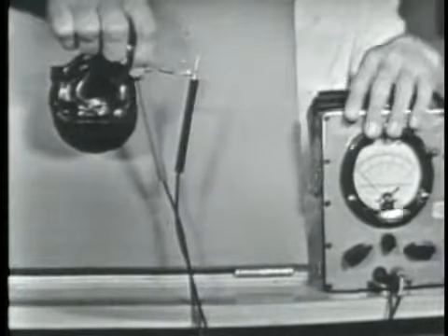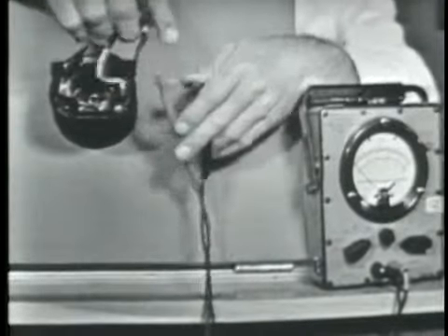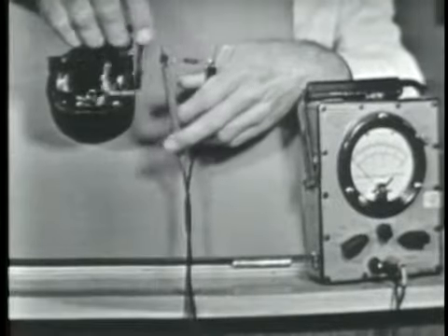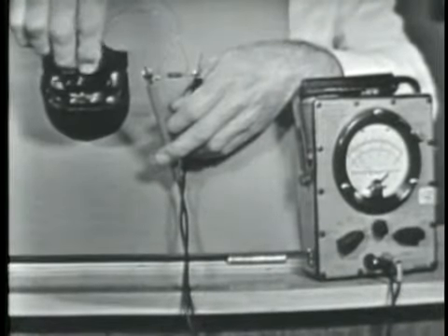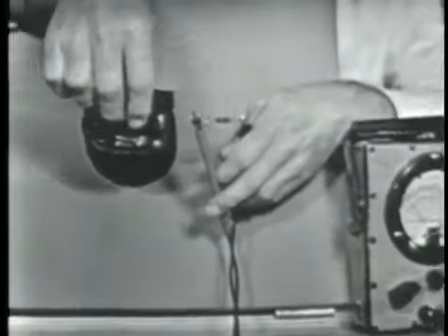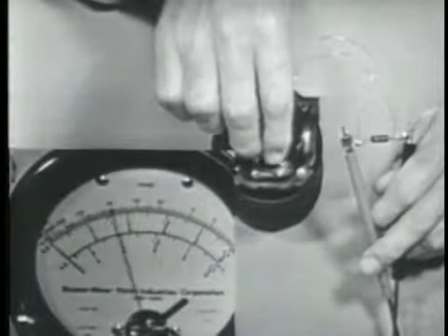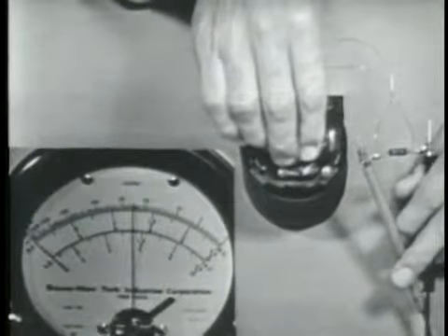All right, now I'm going to take the loop of wire and place it in the field windings. I want you to watch the meter on the PSM6 here. Let me apply the power first. You may hear a little hum being picked up by the microphone because of this magnetic field. Now, as I place this loop of wire into the field windings, like this, you'll see the PSM6 indicating a voltage value.